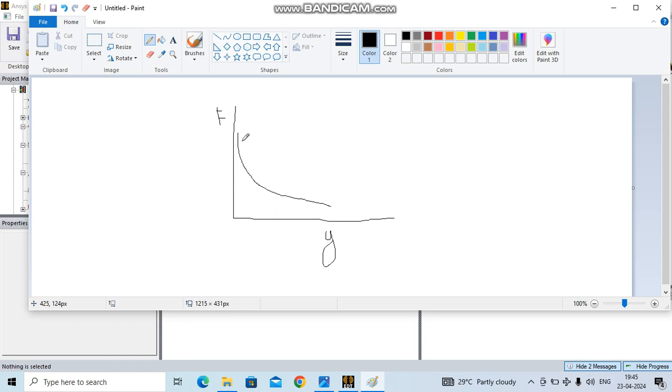So surface roughness plays a very crucial role in the holding force values. You will see sometimes a 30-40% change in the holding force itself. So we have to take care while evaluating holding force through FEA, and we need to know what the surface roughness level is. Thank you.